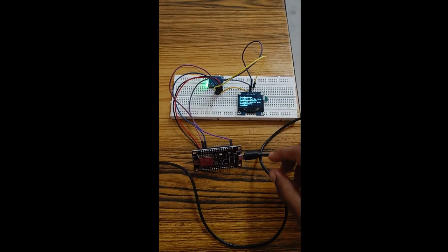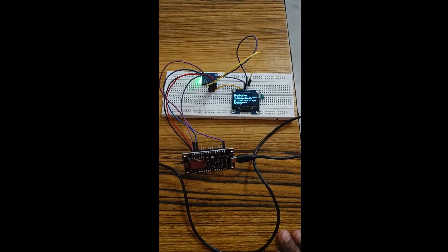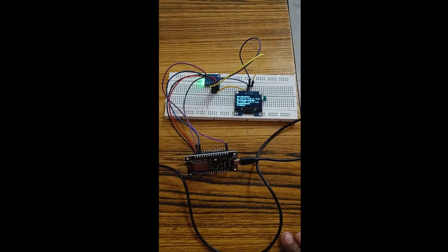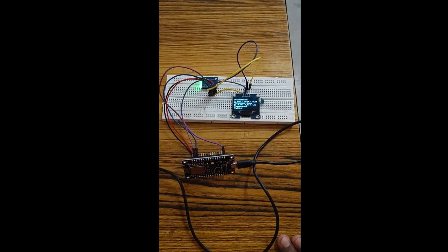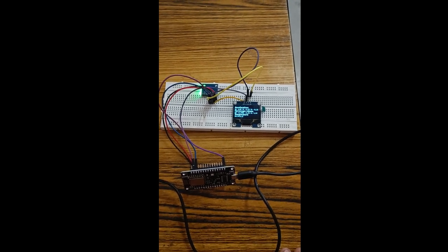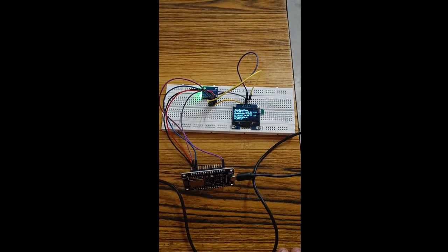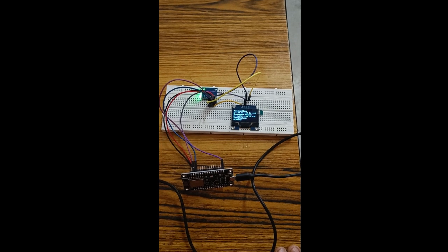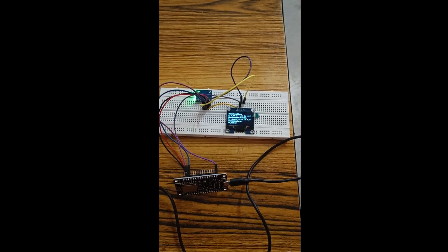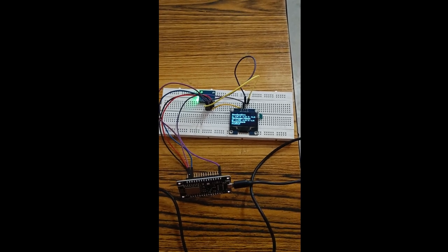This video is taken for testing the vibration sensor. The sensor name is MPU 6050. It is the combination of accelerometer as well as gyroscope value measurement. That means acceleration in meter per second square and gyroscope values in radian per second. For the tilting angle as well as the rotation of the device where the sensor is fitted, it gives the corresponding values in X, Y, Z direction. As well as in this setup we read the temperature of the environment also.